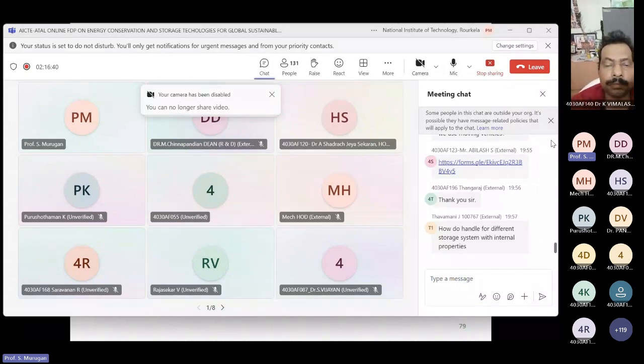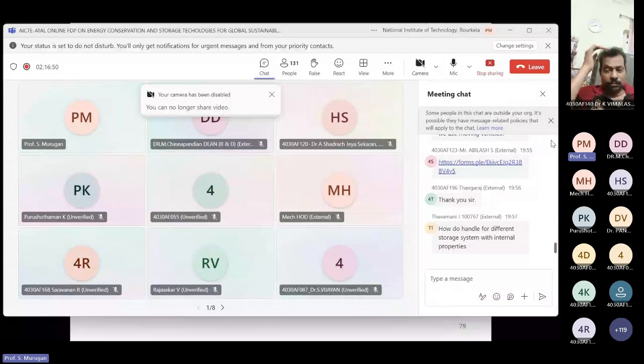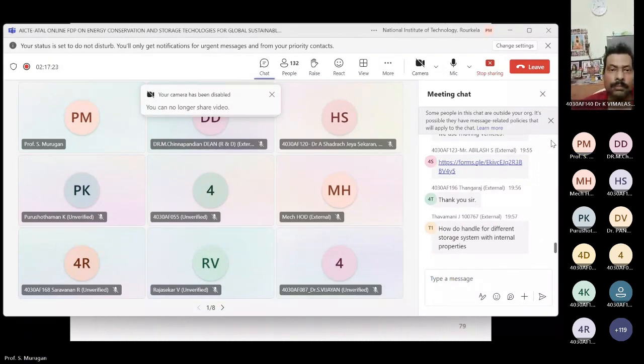That is the basic combustion equation. But it may alter according to how much air you supply, whether stoichiometric air, excess air or less air. Based on that, you can measure oxygen in the exhaust. Suppose more air is supplied, you will get oxygen also in the exhaust, and N2 also. What I recall is that one of my research scholars measured that.